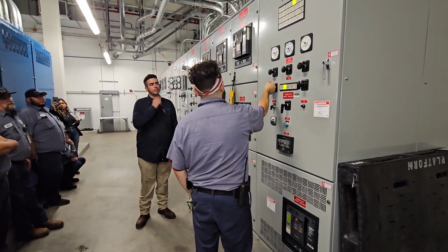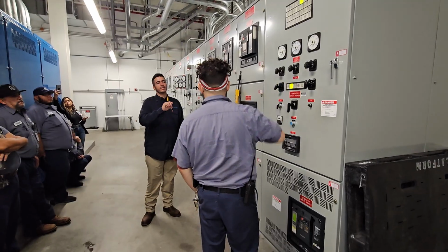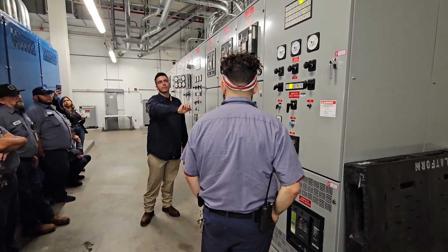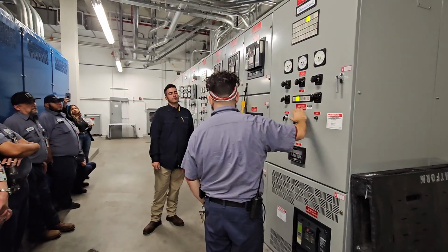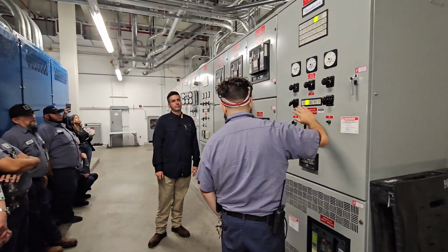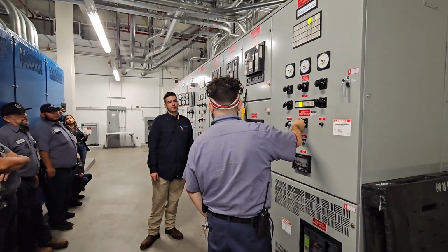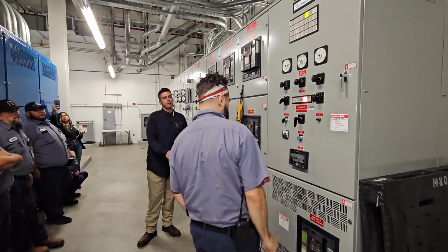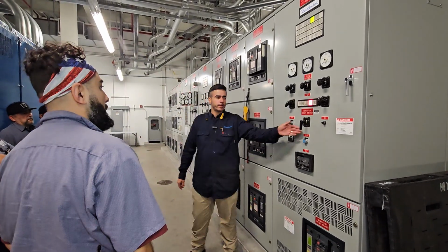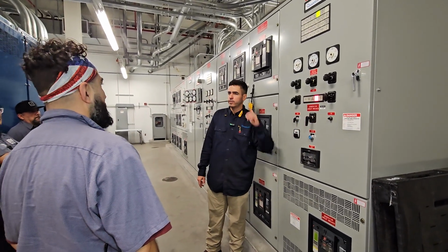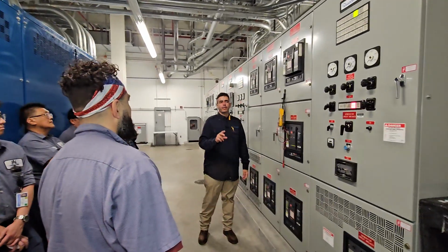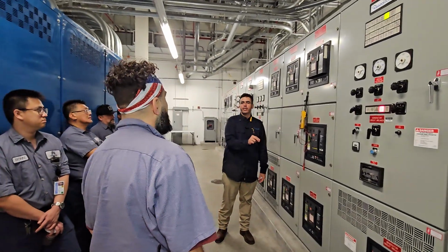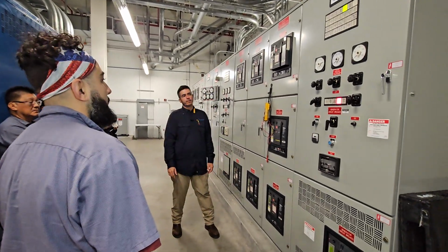So, turn on the synchroscope. That's like your key that enables the breaker synchro control. I have to enable the synchro in order to manually put the generator on the bus. Correct. Okay. So now I close it. Yeah. Let's go. So this is a really quick operation. Close and let go. Once you hear it closing, you let go. Because then you hold the signal and the relay, and it's a sensitive relay. You want to release the signal right away.